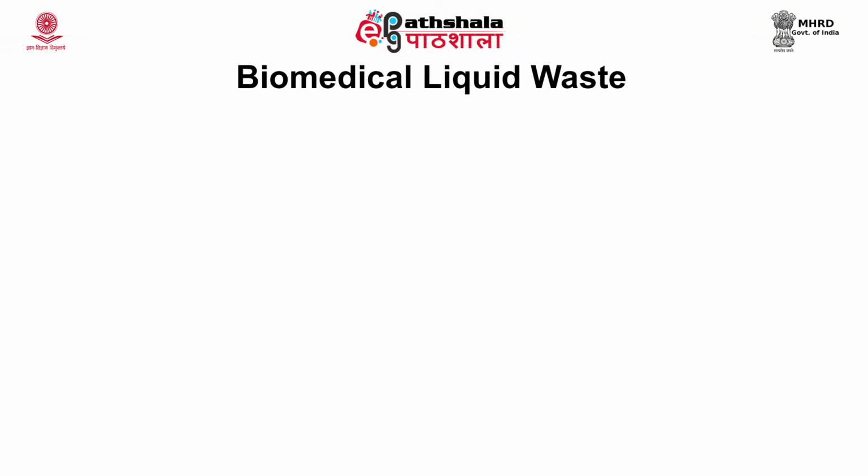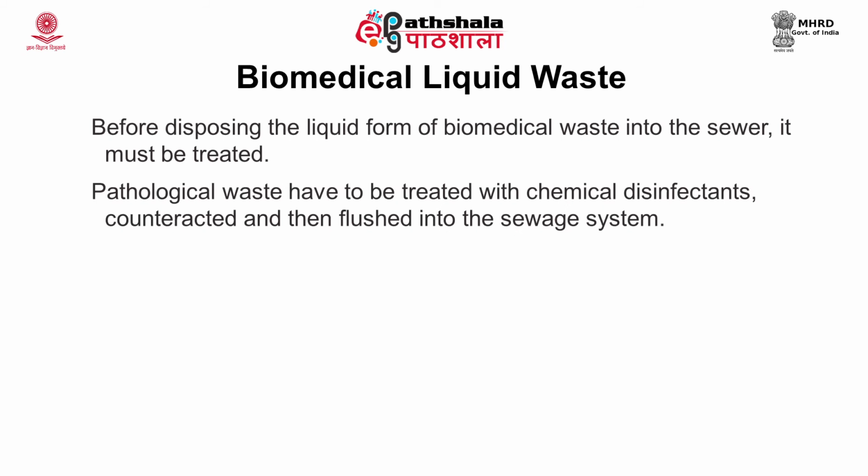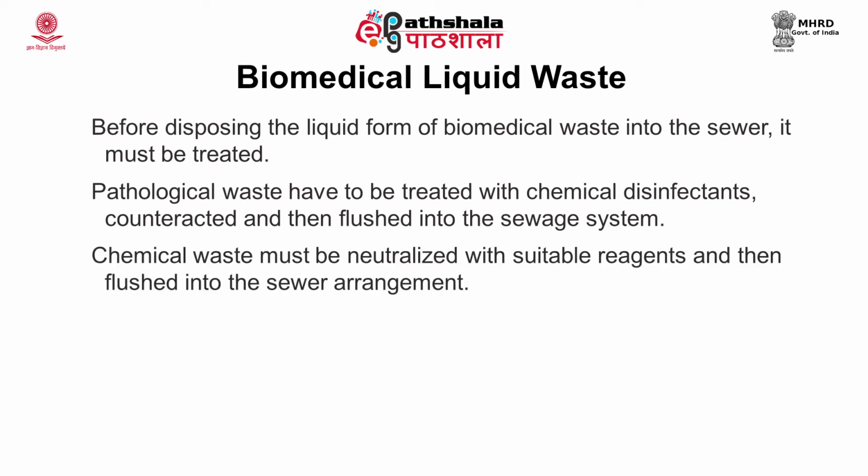So far we were discussing the solid waste which is generated from biomedical waste. Now we look into the liquid waste, which is also a part of biomedical waste. Before disposing the liquid form of biomedical waste into a sewer, it must be treated. Pathological waste has to be treated with chemical disinfectants, neutralized and then flushed into the sewage system. The chemical waste should be neutralized with suitable reagents and then flushed into the sewer.